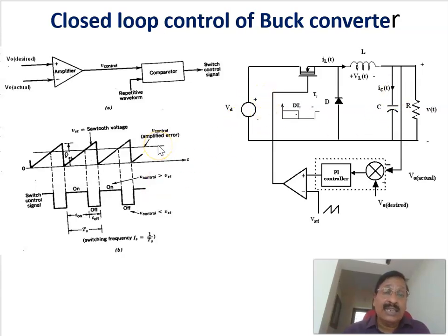That is, by moving this control signal down, the on period reduces and the off period increases, so that the duty cycle will become 33%. That is stabilized to that value, so that you will be getting the output voltage.